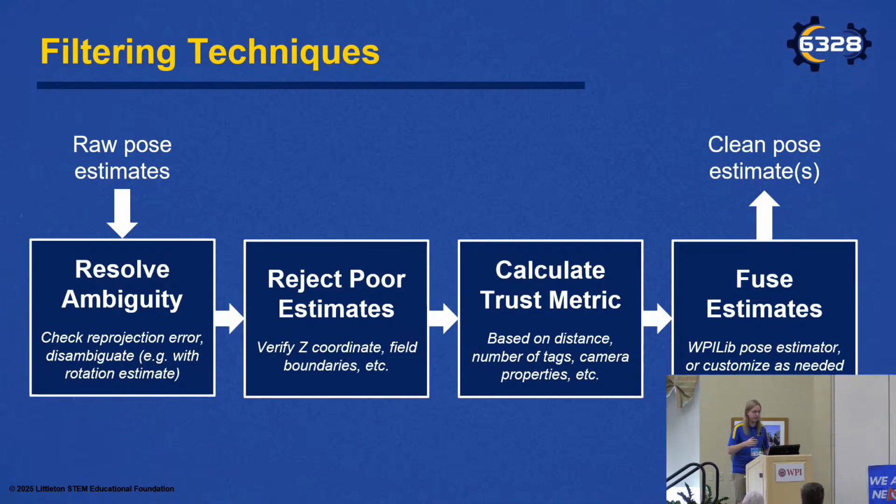Okay, now regardless of the solver you choose, as I said, they all have noise, which means that global positioning always requires good filtering. You can sometimes get away without it for local positioning because you're dealing with a very constrained environment, but global positioning involves multiple cameras, tags at a variety of distances, and multiple kinds of error. You may, from time to time, run into template code that uses vision for global positioning but doesn't properly account for filtering. Generally, as a rule of thumb, you should be suspicious of anyone saying that filtering is unnecessary or an afterthought. It's absolutely critical for global positioning, regardless of the algorithm you choose.